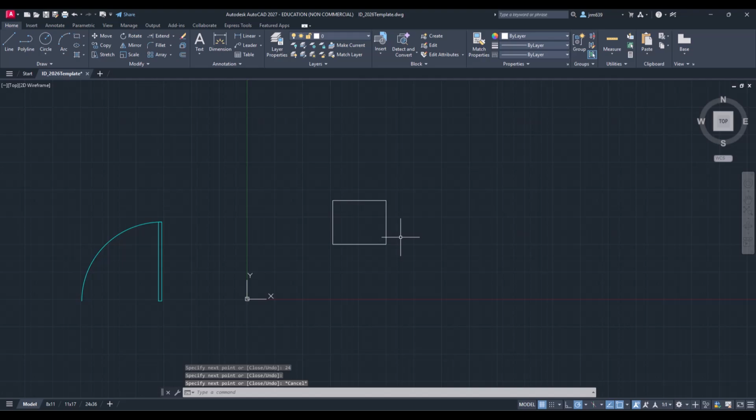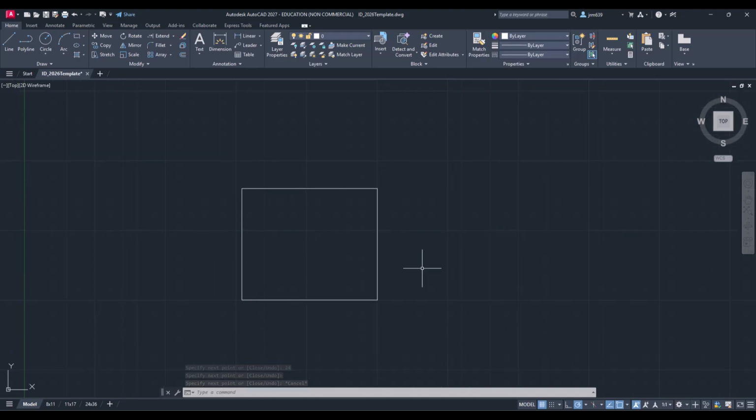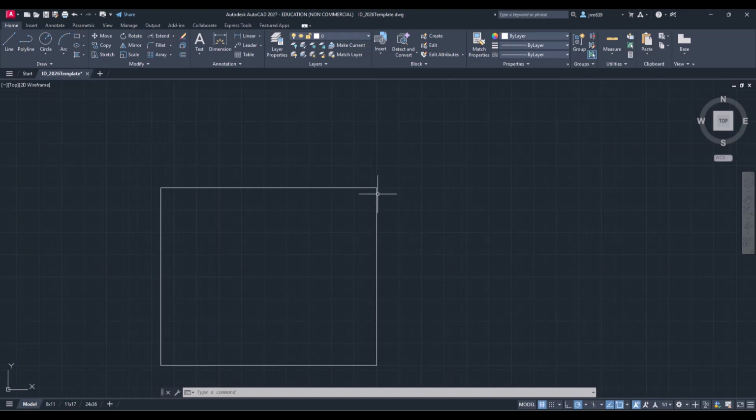So you should have a small mini rectangle right here. This is a great start. So we're looking down on the chair as if it's in floor plan view, and this is the seat of the chair. Now I don't want my chair to be super square, so I'm going to go ahead and taper the back of this chair. I'm going to do that by taking this line and moving it over 1 inch.